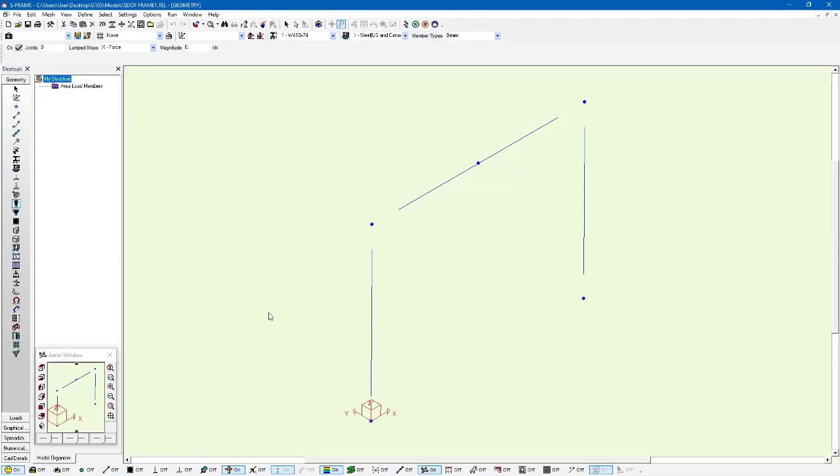Now I'm back in the geometry window and I can look at additional nodes that might be activated. So let's do something first here. I'm just going to change the material from the zero density material back to the original default steel material, which does have a density, meaning that I'm going to be getting system mass from this material density participating as well.